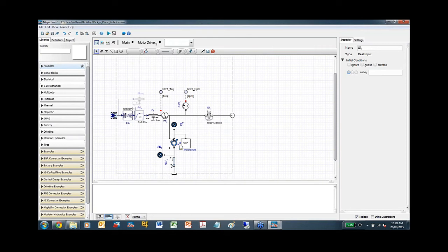I'm passing it through the gearbox, which is here the simple ideal gear component from MapleSim libraries, and then driving that revolute joint. Now, if I have more data like the positions and then angular velocity or accelerations, I can replace this simple position driver with components such as the move component, which is accepting all these 3 inputs.